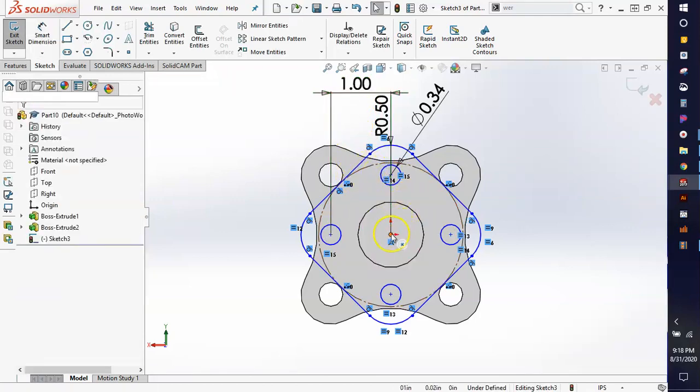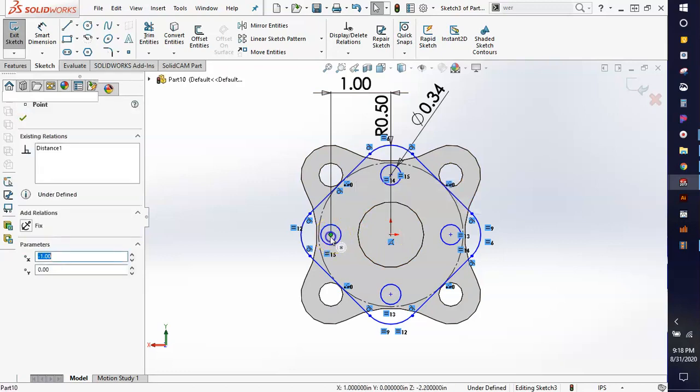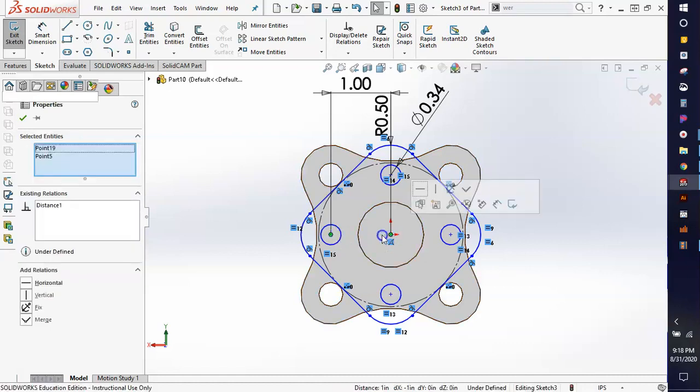Okay. And in order to fix that, we just need to hit Escape off the Dimension tool. First, let's select this center point, hold Shift and select that, and let's make that horizontal. You could also do this one vertical, but if yours was just slightly off and rotated, this projection line or extension line wouldn't have gone through that middle. Now it does. So you can see this is all fully defined already just off of the simple measurement.